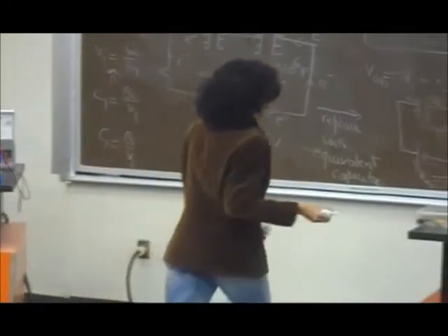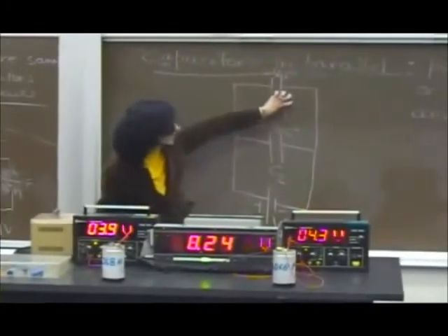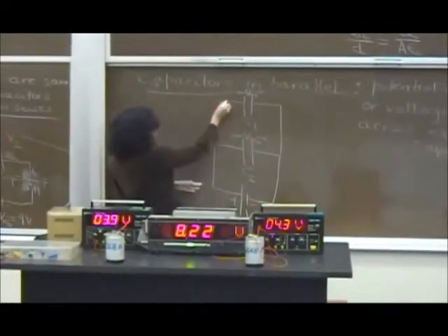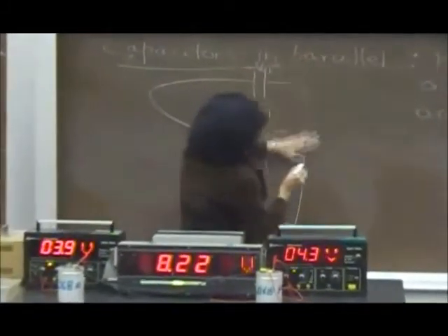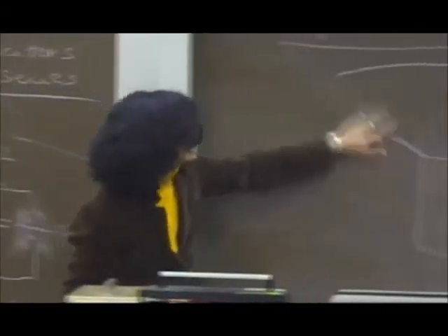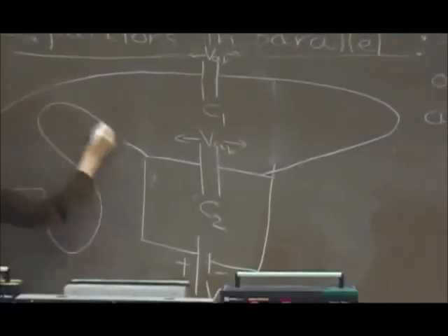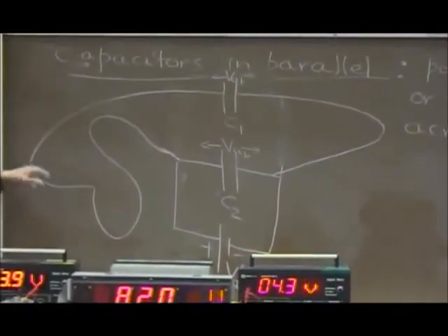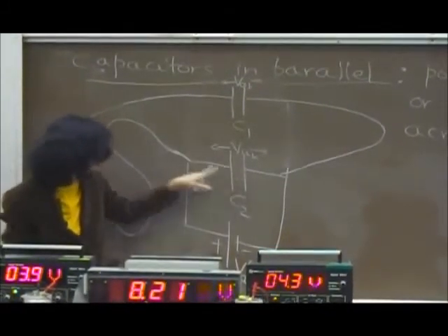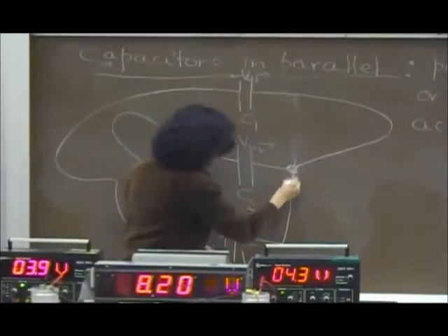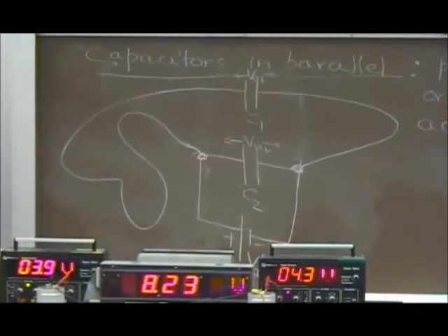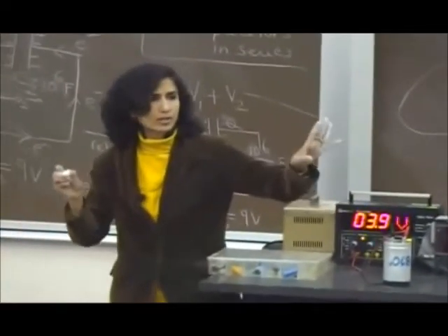So in this circuit the only capacitances are due to this capacitor C1 and this capacitor that has capacitance C2. If I change this circuit and make this wire longer like this, have I changed anything? No, I haven't changed anything. Even if this wire looks like this, it doesn't matter. We are not worrying about the capacitance of the wire. The only thing we need to worry about is how they are connected to each other. The junction is something you should worry about. So long as the junctions are in exactly the same place, how long these wires are is not important.